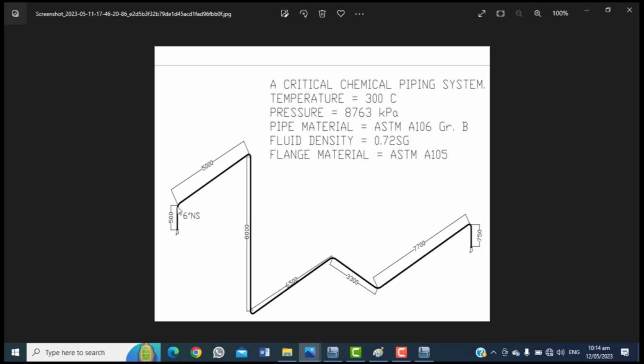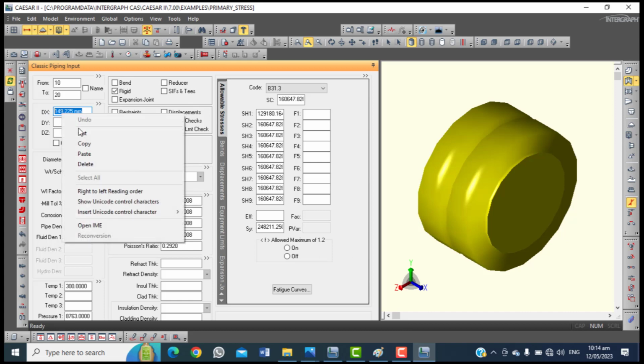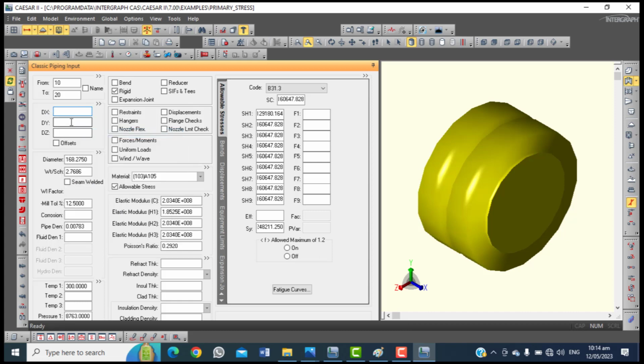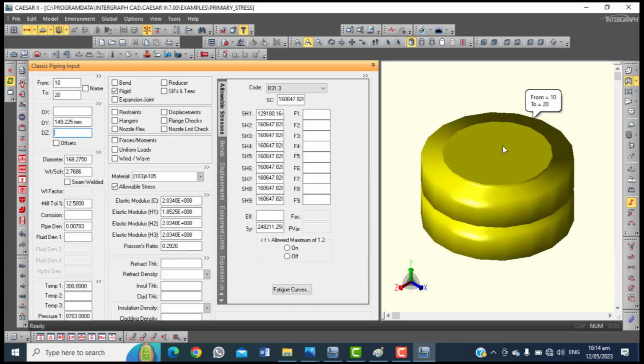All right, but I'm going to have a short pipe of 500 millimeters, which stops at the center of the adjoining elbow. So we'll go back to this, but we're going to cut this from here. We're going to cut this value and paste it here. All right, so we have this value pasted here, and then it is facing in this direction. This is a class 900 flange.